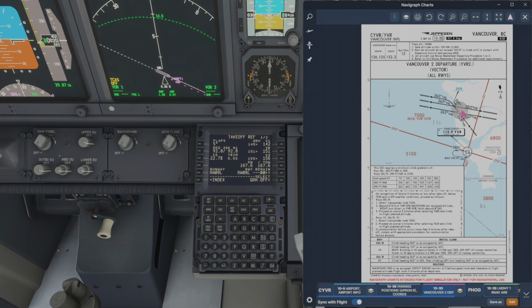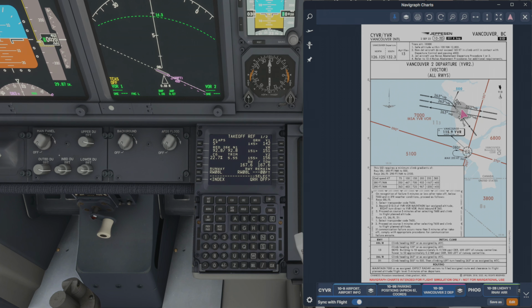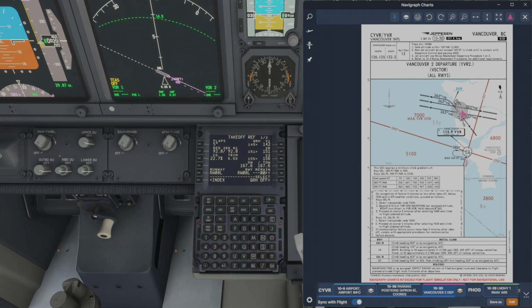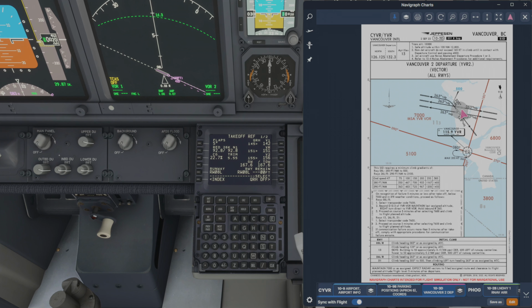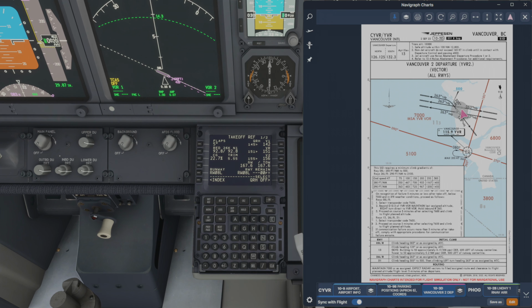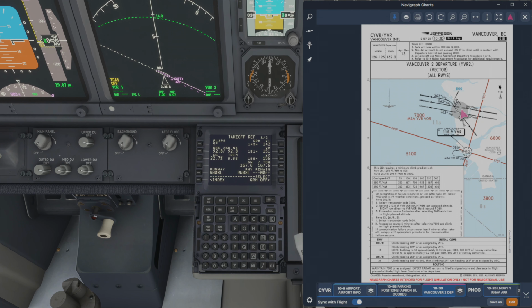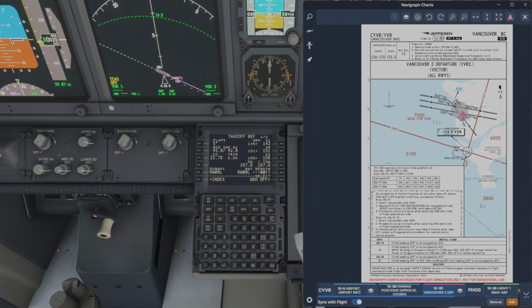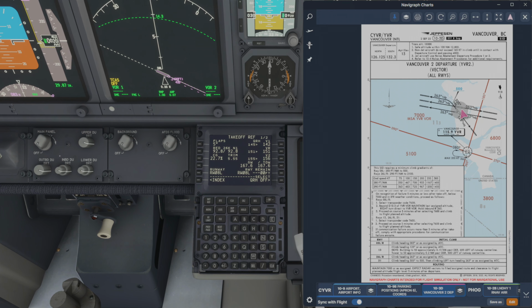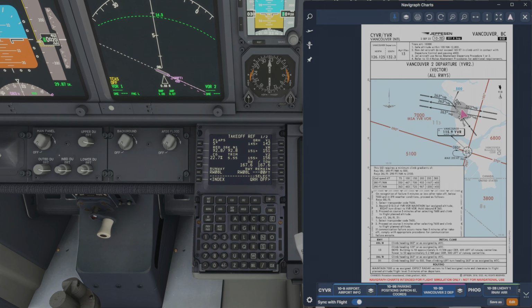I'll call reject. Close the throttles. Use maximum reverse thrusters. If we're able to clear the runway, we'll clear the runway and we'll assess the situation. You'll coordinate with ATC. I'll inform cabin crew. Any major malfunction after V1, we'll continue with the takeoff roll, climb to 4,000. We'll level off at 1,000 feet above ground level and accelerate the aircraft to 250 knots, assess the situation.